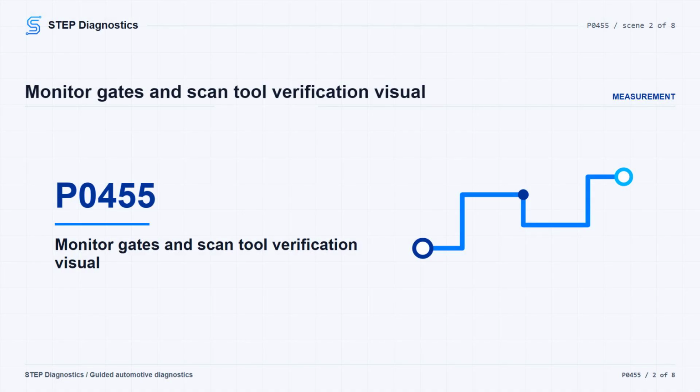Before judging the EVAP test, understand how this monitor is gated. The small leak monitor uses an engine on/drive cycle for a minimum of 2-5 minutes, and the engine on timer is clipped to a maximum of 26 minutes on any given trip. There is a 12-minute delay time where the PCM ignores ESIM switch input. On the engine off side, the event can reach a maximum time of 17.5 hours without an ESIM switch closure, and the accumulation timers are engine on 100 minutes and engine off 70 hours.